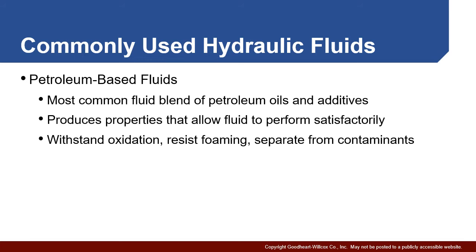It tends not to foam, which is another big problem, and it's not so thick that contaminants are trapped in it. If you leave oil in the reservoir for a period of time, the contaminants will separate out and oftentimes settle to the bottom of the reservoir for eventual removal.